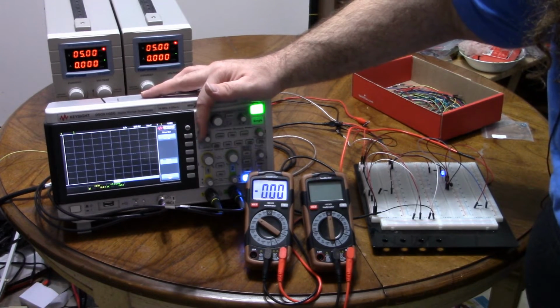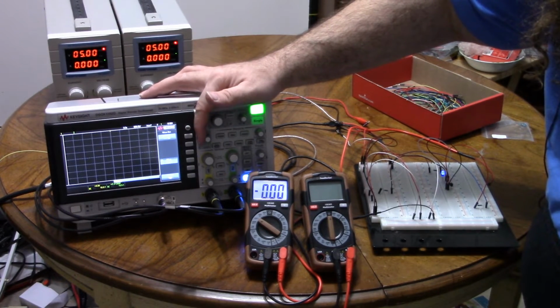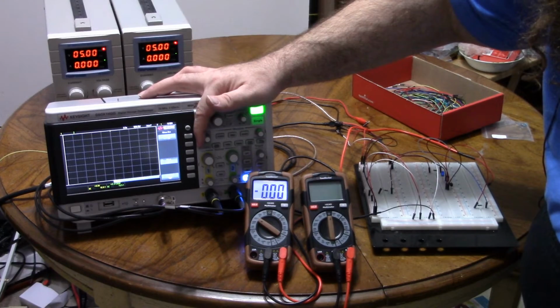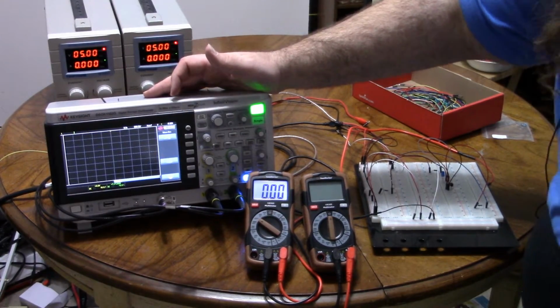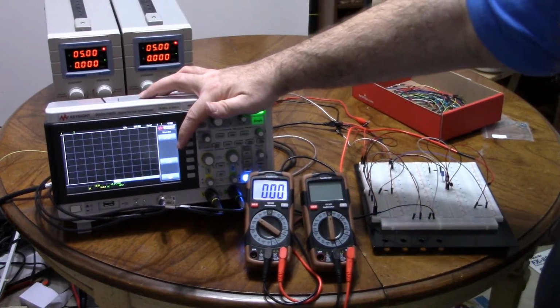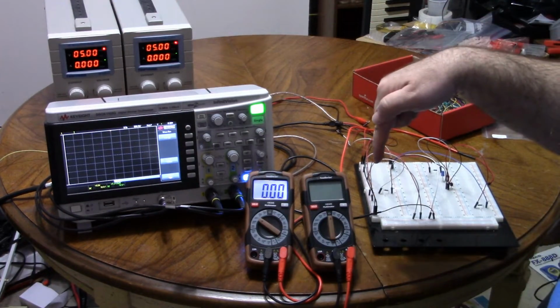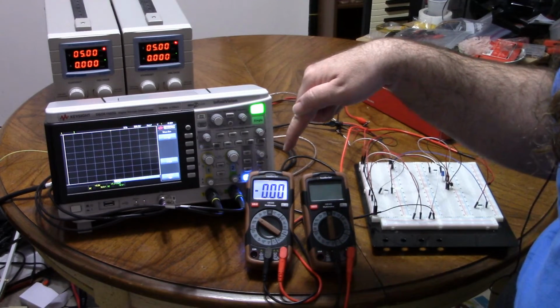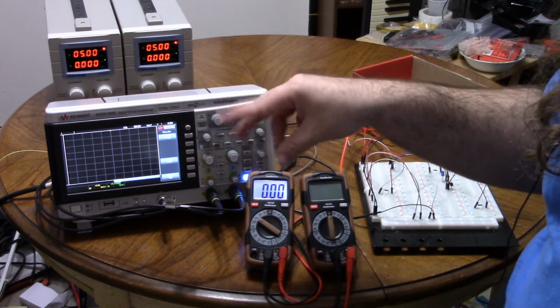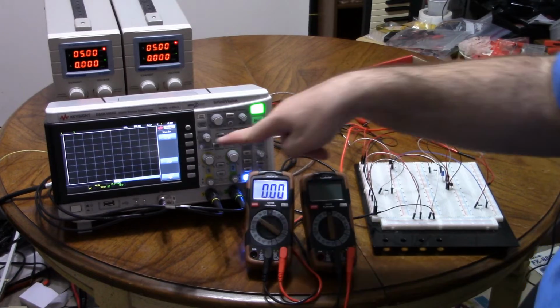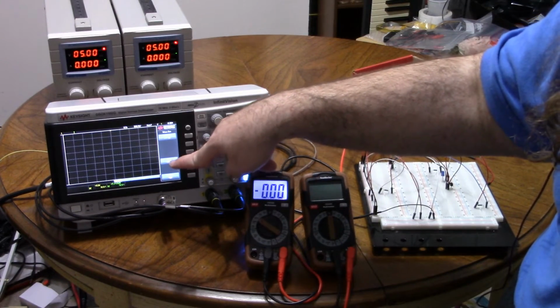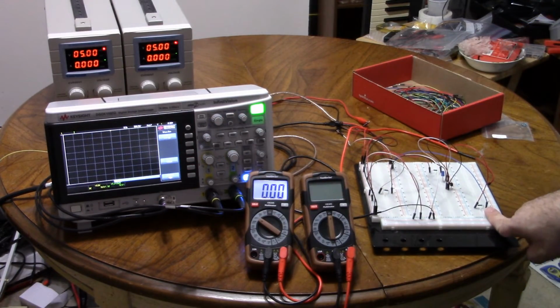And oh, it's starting to dim. Do you see? Now it's changing in intensity. And if I turn it to about there, it looks like it's completely off. And what do I have? Minus 4.5 volts. So recall, we were getting minus 1 volt to minus 0.45. So that's about 0.55 volts for the base to emitter. Well, we're about 0.5 away from negative 5. So interesting that, isn't it?